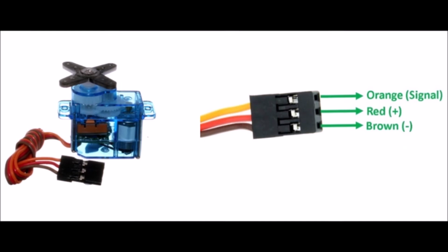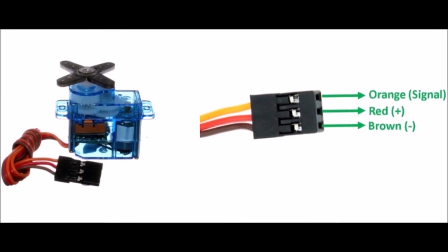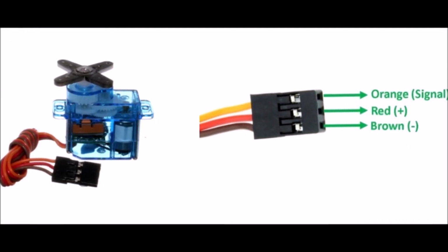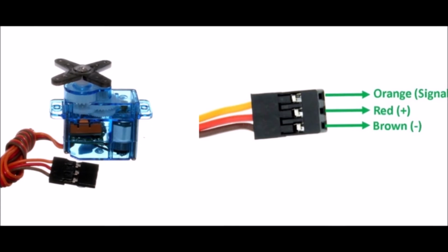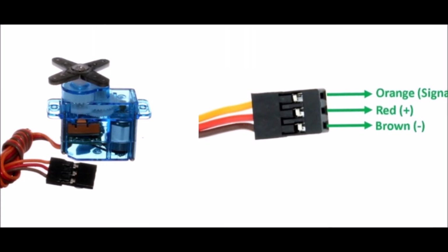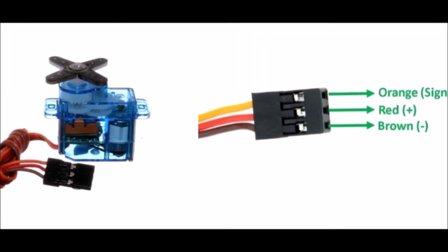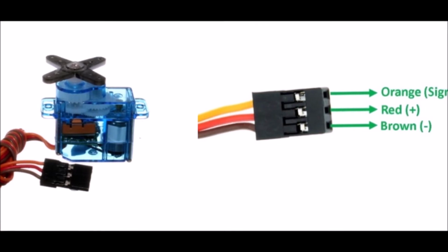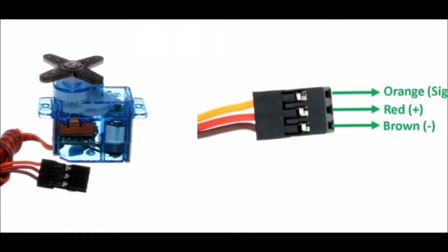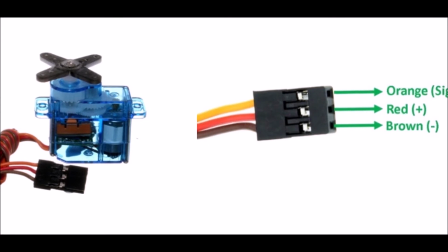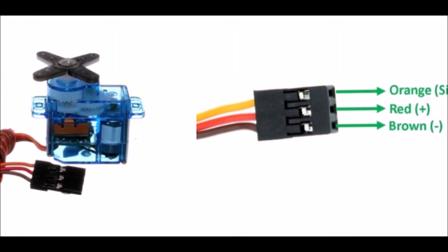A typical servo motor has 3 connections that are brought out through a header. There's the ground connection, the power connection, and the signal connection. So we can take our 555 timer circuit output and connect it to that signal input on the servo drive and command it with this control signal.